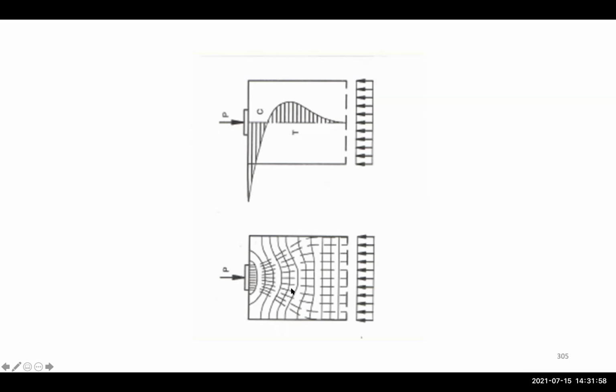For the general area, as you can see below, we have the force applied. You can see how the stresses would happen here, and then after a certain distance, they will stabilize, and then we will have uniform compression after that. And that's the goal of the PT, having more compression force in the slab to prevent, of course, the tensile forces in the concrete, which will lead to cracking.